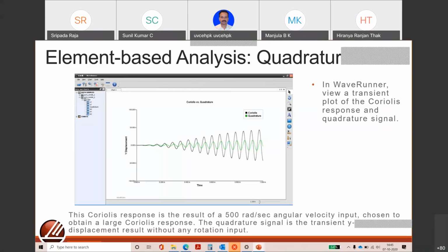Now suddenly, if my reference axis is in y direction, then my device, which is vibrating exactly horizontal, changes its direction. So that's when the distance between the two elements in the z direction also changes, for which there is a change in capacitance. So that capacitance change is seen.